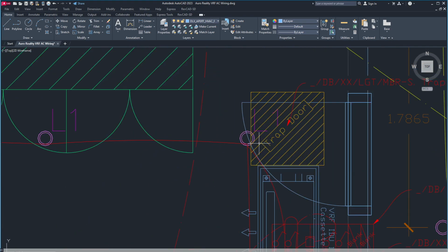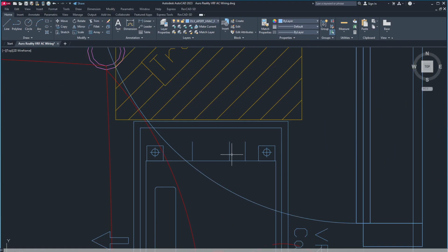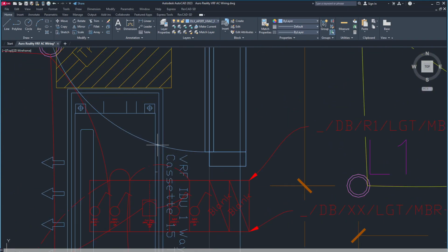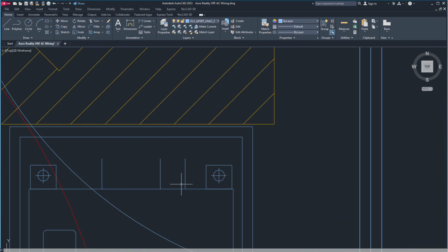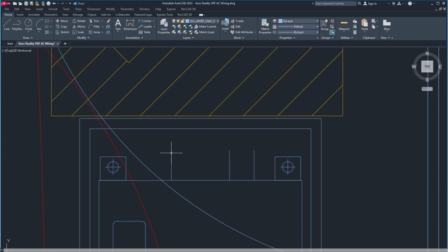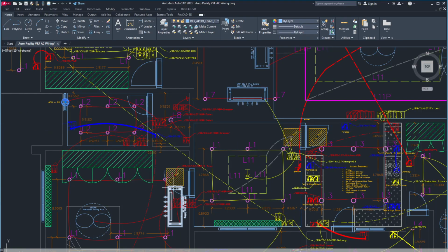Okay, let us get back to this. So this AC, what does an AC indoor unit have? It has a liquid line and a suction line. The suction line will discharge the refrigerant to the compressor. The compressor is placed here. The liquid line: refrigerant is coming from this, entering the evaporator, and from here it goes to the compressor for recirculation. This is the water discharge. Because of condensation, water is formed. The water has to be removed, so we have to draw it like that.